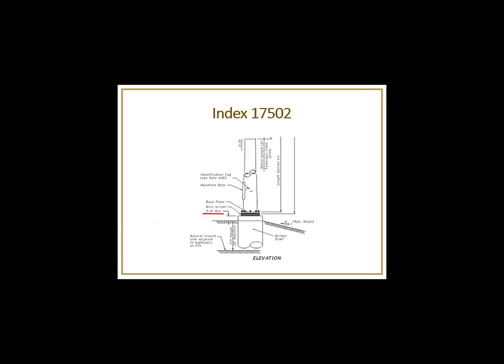This is not a change. I've underlined here what the requirement is. The index shows that the shaft should stick out of the ground 2 feet above the existing terrain. Now, we're not sure why, but when you go out and start looking at some of these in the field, we see that they're not done correctly. That 2-foot minimum is not being followed in the field. We can only guess why that is not being done.